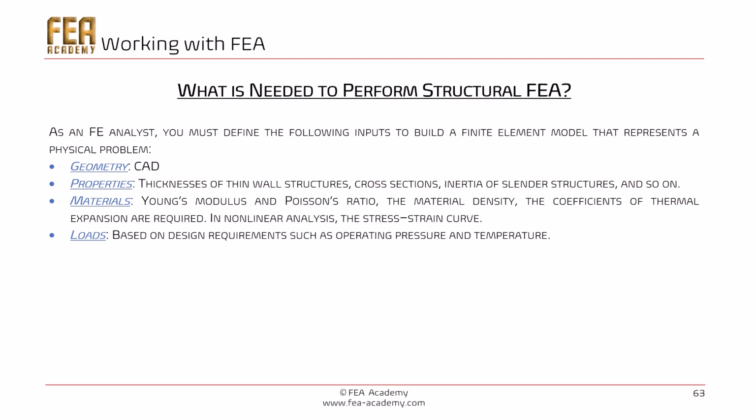With more complex loadings, the loads are sometimes defined by a dedicated group with expertise in the definition of the specific loadings applied to the structure. In this case, based on a given discretization of the structure, a discretization of all the loading conditions is provided to the FEA analyst.